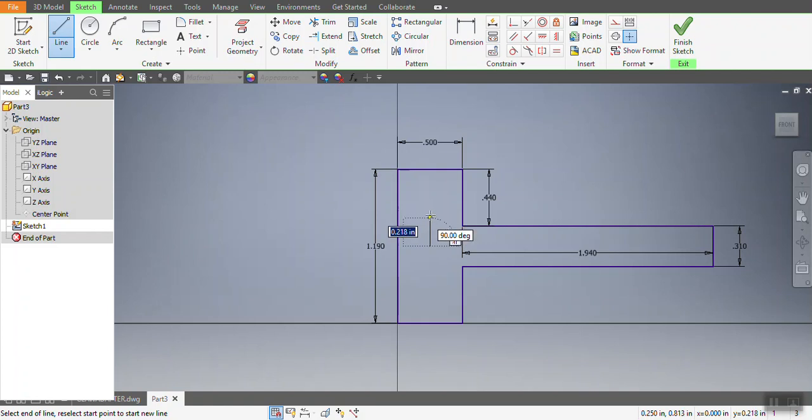Knowing this ahead of time, I calculated the location of the center of the hole should be 0.28 inches higher. So I'm typing 0.28, enter. Okay? This is the center of the first circle. I'm moving my cursor down, and the location of the center of the second circle would have been 0.56. I'm typing 0.56, enter. Okay? So enter again, I'm out. So this line indicates the geometric locations of the centers of the two circles. That's very important to know before drawing the circle.